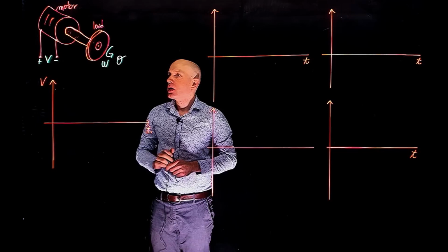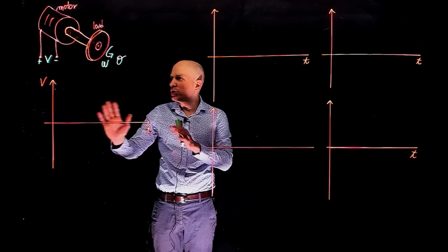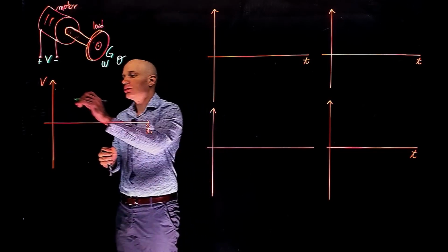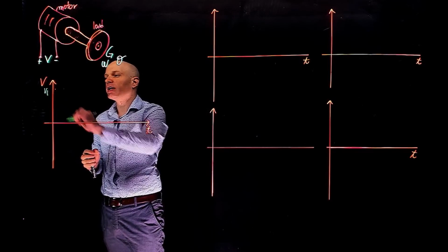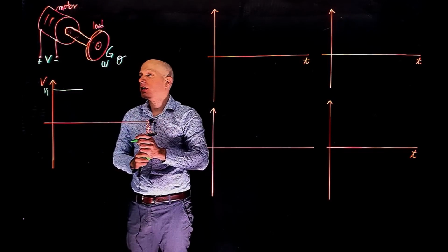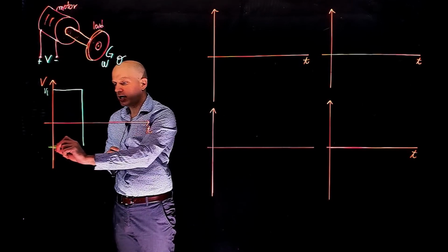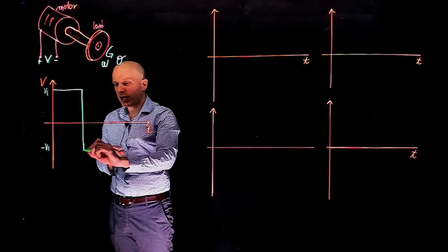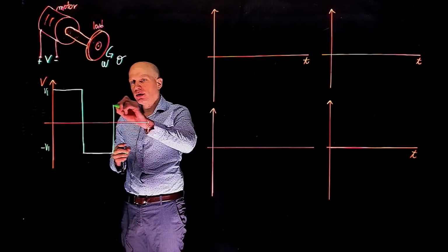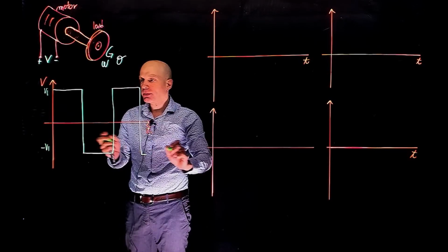It's simply a gain. Of course, we know that that assumption doesn't hold true, but this is just for simplicity here. Let's assume that this motor is actuated with a voltage V that we are going to choose to be a square waveform. We're going to apply V to the motor. Let's call the magnitude of that input V1. We're going to hold that voltage at a constant value for a certain period of time, and then reverse the voltage to negative V1 and hold that for the same amount of time before again we switch back to V1 and so on. What happens to the motor?